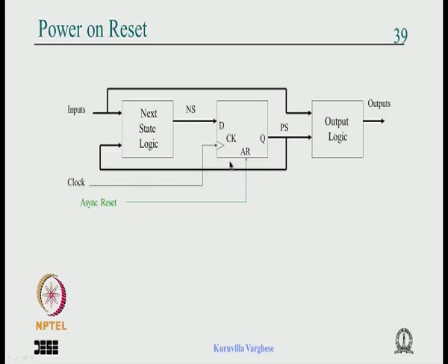Okay. So you can treat this as a kind of process for a flip flop, where this reset is implemented along with that flip flop as the asynchronous reset of the flip flop. Suppose we take the case where the flip flops in the technology, whatever the technology used, be it ASIC or an FPGA, do not have this reset available, so there is no reset at all in the flip flop. Then what we have to do is introduce a synchronous reset.